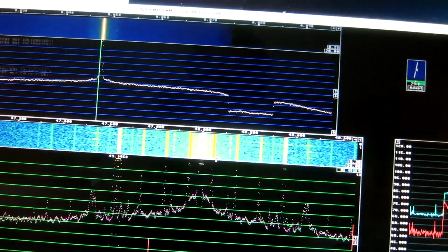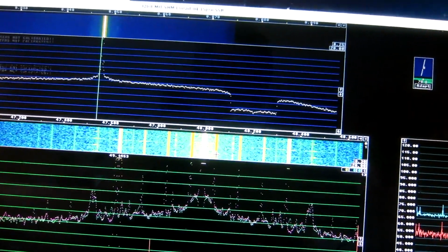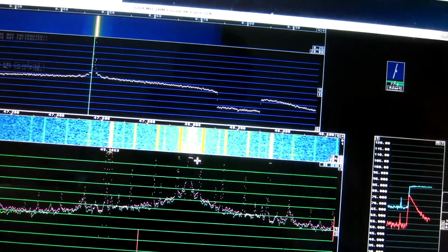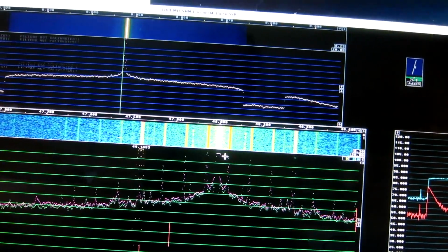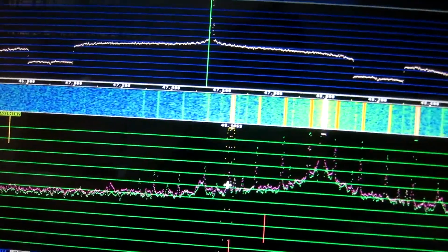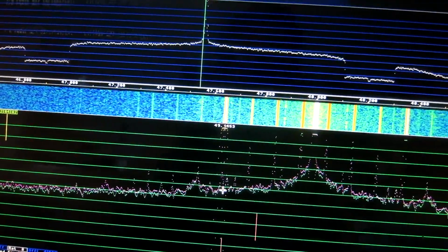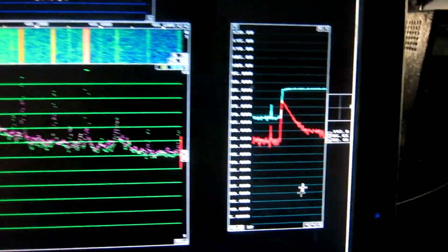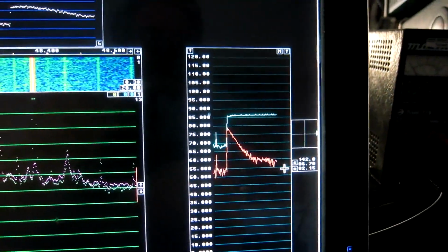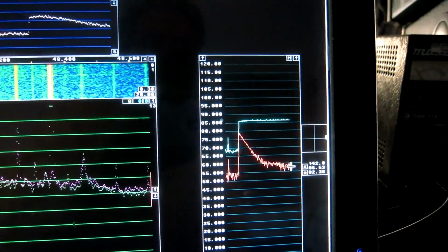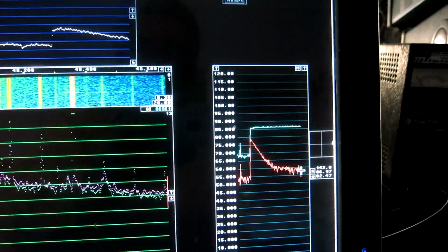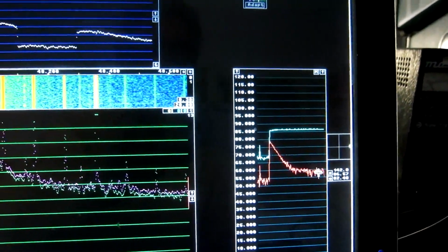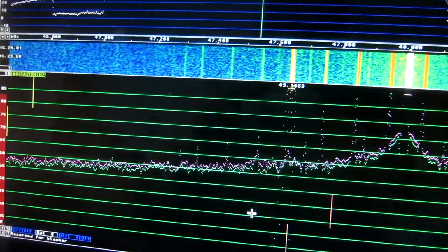So these sidebands that originate in the mains frequency are both amplitude and phase modulation, while the signal generator is pure phase modulation. And you can see here the adaptive thing makes a very good suppression of the AM component.